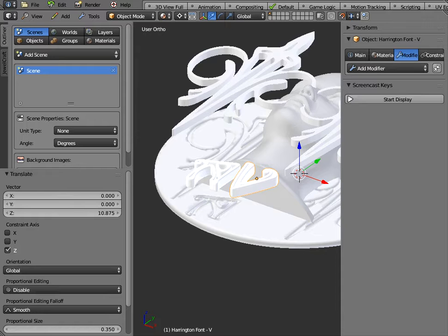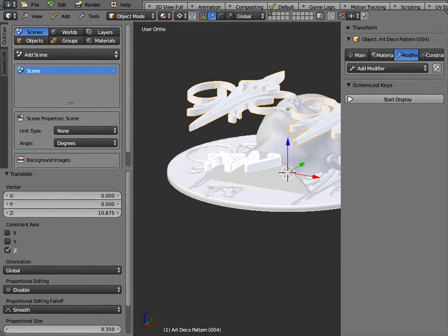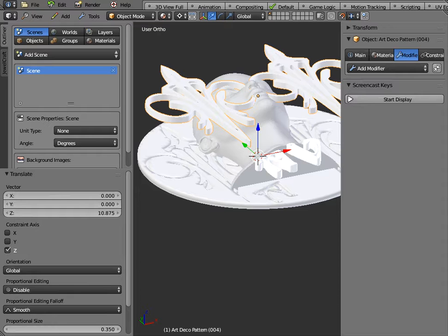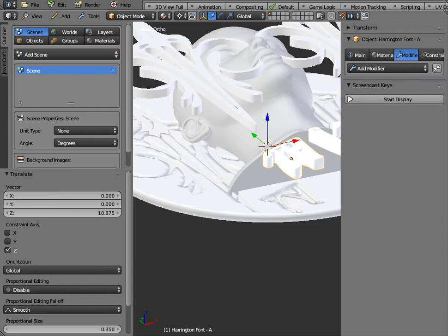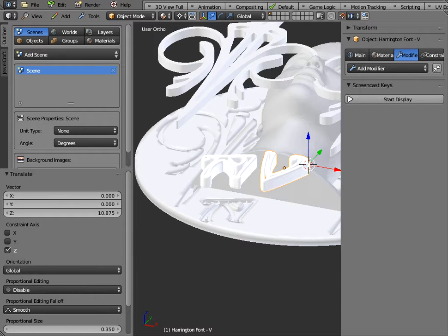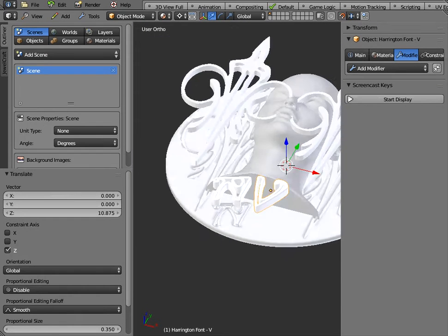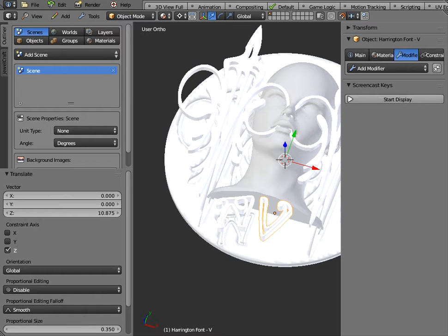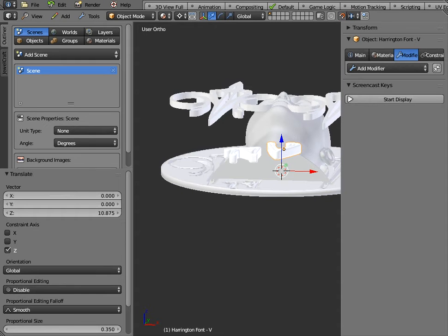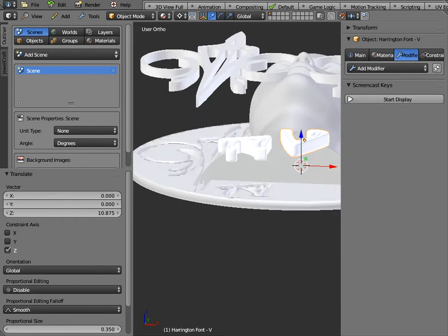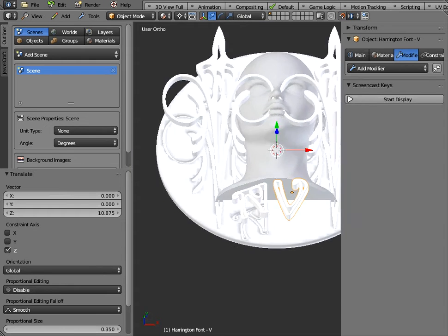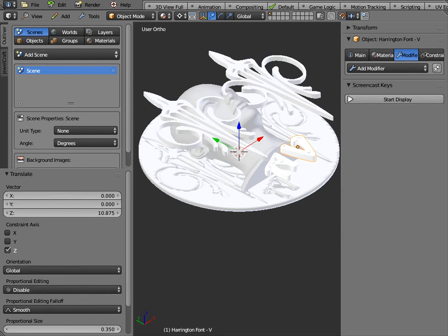If you want to engrave, use Bezier curves, and particularly use 2D Bezier curves. I would not use Nurbs curves. You can see it worked with the A, but it didn't work when I tried to do it with the V. Okay, so Nurbs curves are really great for joining together and for embossing, for putting above objects, but they are not good for engraving like this. Alright, so that's one important thing to understand about Nurbs curves and how they can be used in Fluid Designer.